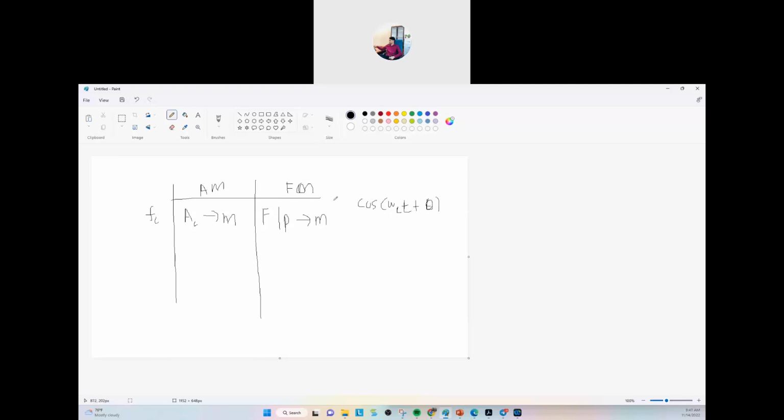That's why frequency modulation we call angle modulation, because whatever changes, in terms of the phase or the frequency, it will impact the entire angle, because it's cos theta. This is a cos angle, so that's why we call it angle modulation. Frequency modulation can be recognized as angle modulation, meaning the entire angle, or phase modulation. Phase modulation means only this one.